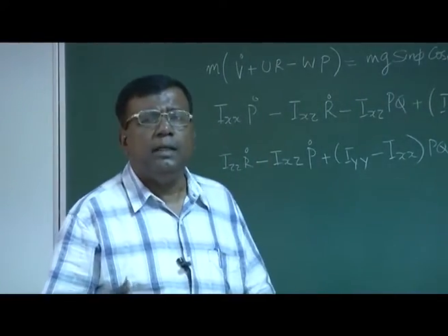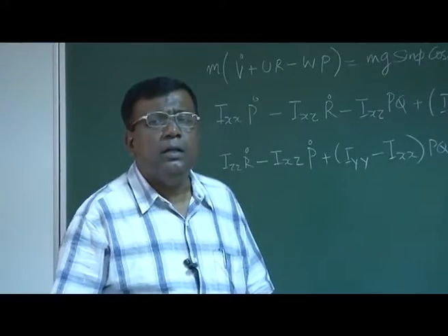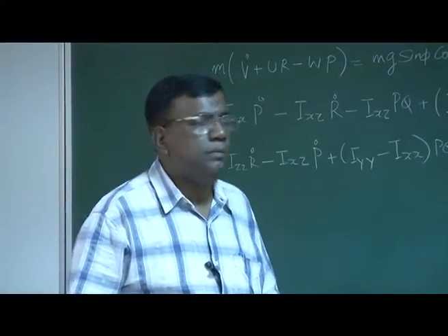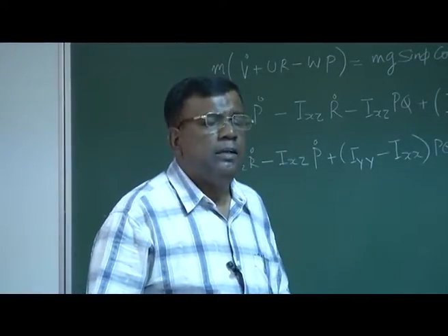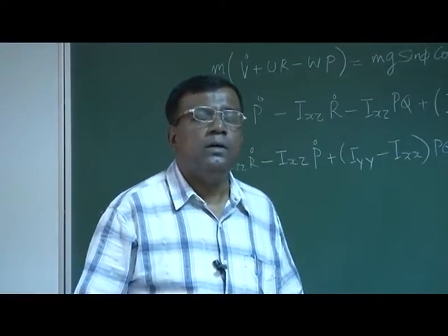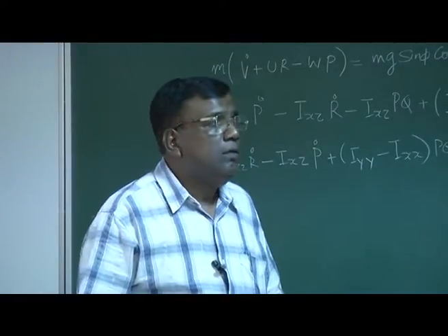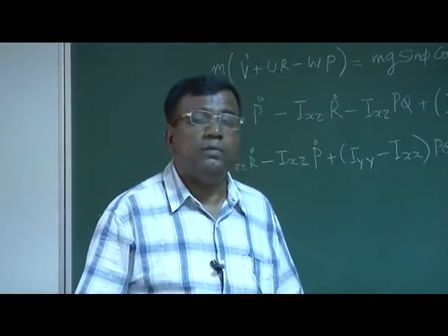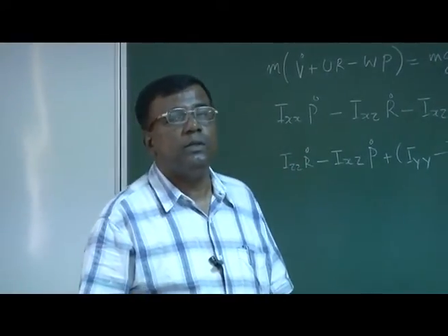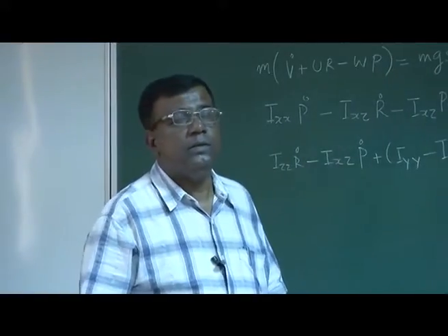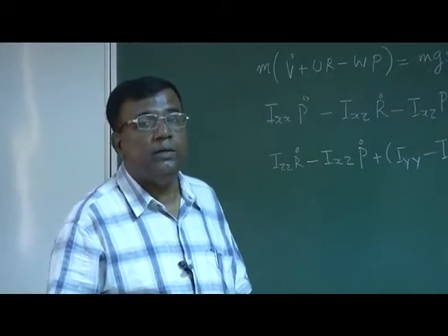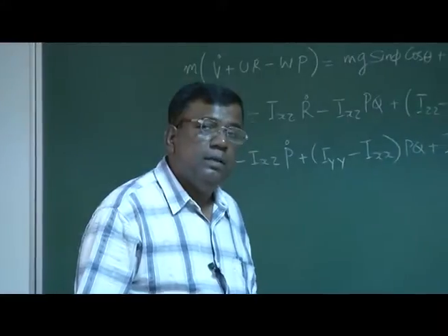And then we had different steps, like how to model the perturbed aerodynamic forces, especially Fx and Fz. For that, we derived a mechanism. Some steps were shown to you. And finally, we got a matrix. When you took the determinant equal to 0, which is the characteristic equation, we found an equation of the form as^4 + bs^3 + cs^2 + ds + e = 0. Then we found the roots, and from there we tried to interpret the short period mode and the phugoid mode and find their natural frequencies and damping ratios.